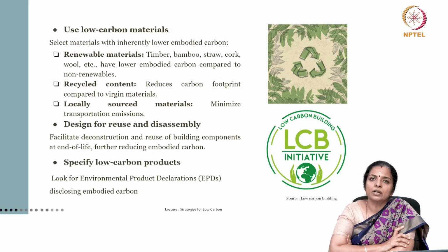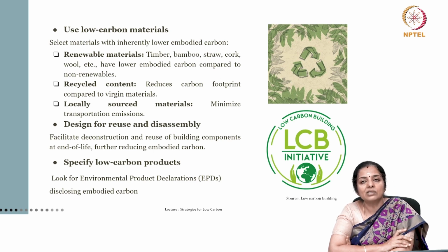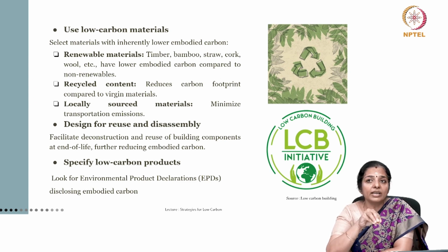These options include using low carbon concrete or even alternate structural systems, like using mass timber or hollow core blocks. Now, using low carbon materials, it includes that you select materials which inherently have low embodied carbon in it by virtue of its source from where you extract or manufacture.